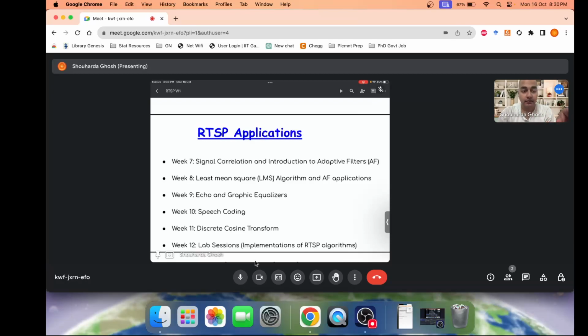But in case you take mu some high value, not very high, but high enough, then what you will observe is that you're settling down to some mean square error which is above the noise floor. Why did it happen? Because you're not giving enough iterations, or you're not converging down to the W optimal. And if it's too fast, then you may diverge up the error gradient surface. The bowl shape or the parabola that I showed you in 3D, it's called the bowl. It's called the error gradient surface.